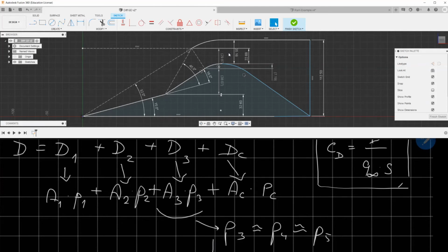Yeah. As I said, you make this estimation, validation. You need an approximate value. You don't need the exact value until you know the last decimal point. Take something average. In my case, the Mach number changes along the section since the area changes, though not by much. You can use the average. You remember probably the theorem of average, that allows us to substitute variation of any parameter inside integral by its average value.